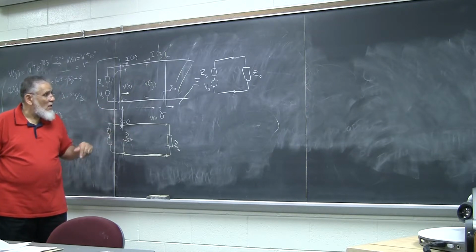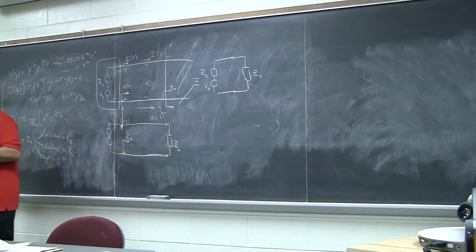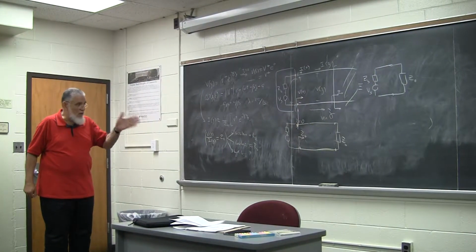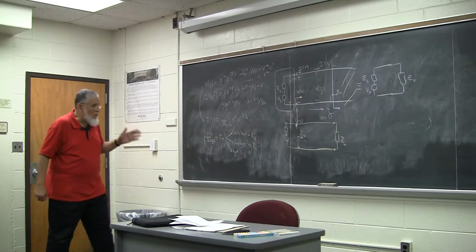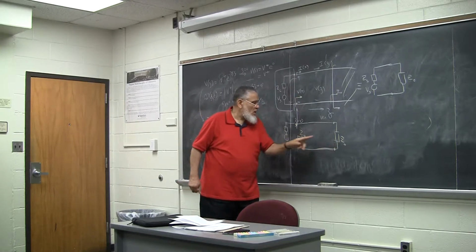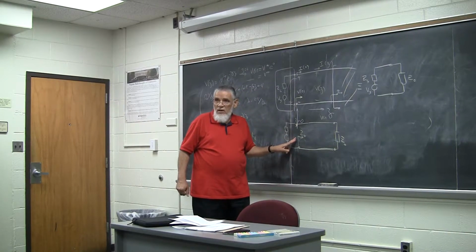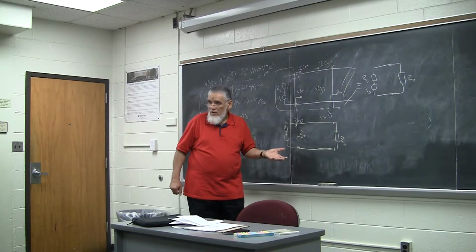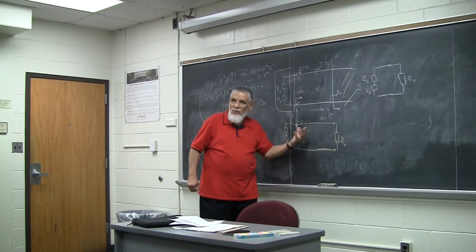So these are several ways to look at Z0. That's your impedance or characteristic. That's why it's a characteristic number. It's unique for this particular line, for this given dimension, for this given material at that particular frequency. The characteristic impedance is 50 ohms. So if you terminate in 50 ohms, it will look like 50 ohms here. And that kind of situation is what we call the matched termination. If you terminate in 50 ohms, your signal will go indefinitely.